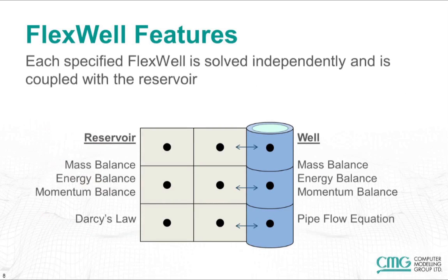Just as the reservoir is discretized, the wellbore is also discretized in FlexWell. Each specified FlexWell is solved independently and is coupled to the reservoir. Just as we solve mass, energy, and momentum balance in the reservoir, we also solve mass, energy, and momentum balance equations in the well. Darcy's law dictates the flow in the reservoir, whereas pipe flow equations dictate the flow in the wellbore.